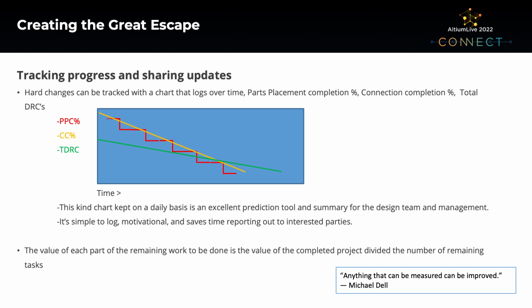Don't reuse your reference designators. Reannotation can take place after the new parts are placed. It should never be done before. Do use rooms, because that's going to help you sort your components out. Group like functions on the same page of your schematic, and group different types of circuits on different pages. And then keep an ECO list, because that's going to help you track why things changed or why they were added.